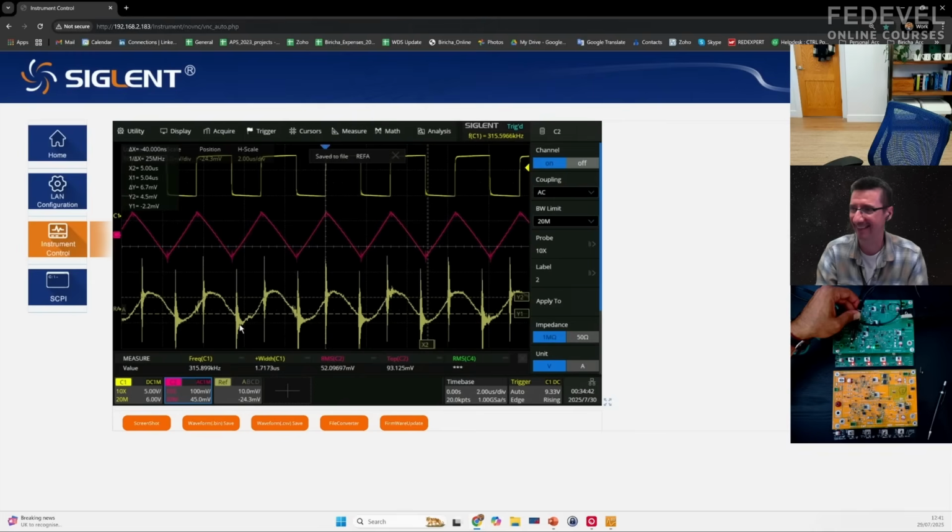And the really interesting part is that the ripple voltage across the capacitor is not a sinusoid or a pseudosine. It's a triangular wave. It is identical to the ripple across the inductor in terms of current. This is interesting. So what is creating this ripple? A resistor or a capacitor? We know that the current is triangular and the ripple voltage is also triangular. So that's Ohm's law, right? It's clearly the resistor, the ESR of the capacitor, that is contributing the most to the ripple.